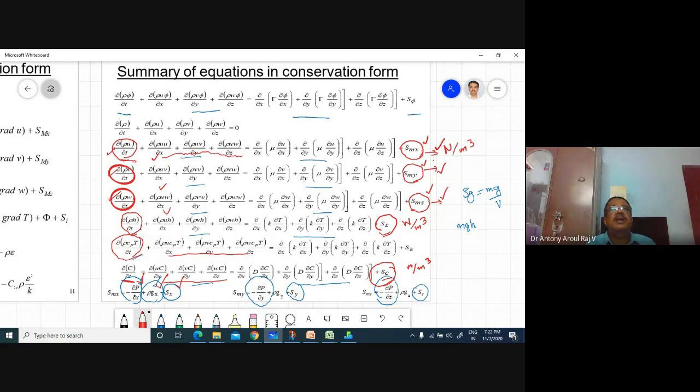If it is taking the property species from one place to another place, then we call that species convection, or convective mass transfer. If it is taking the property of momentum, then it is called convective momentum transfer. In convective momentum transfer, only if there is acceleration or deceleration, these terms will be there. So this is very important. Please try to understand these terms.